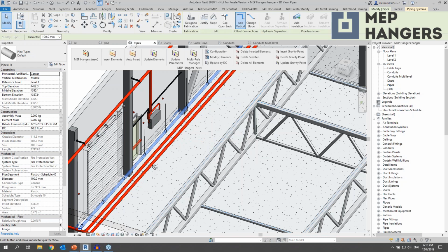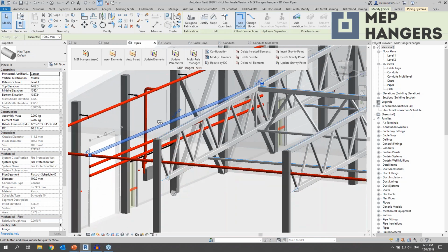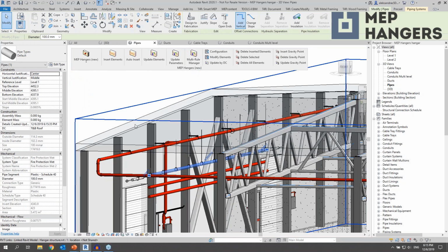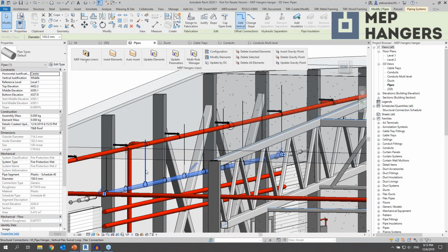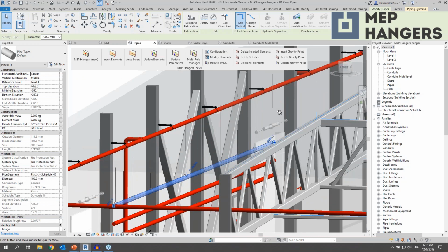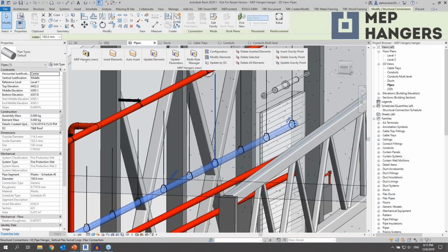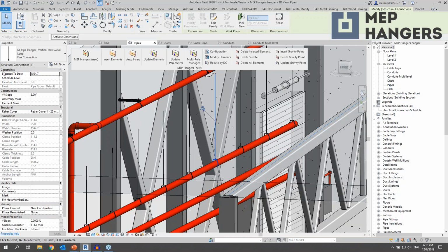And all our hangers are made such that, as you see, the roof is with inclination, and all the rods are getting longer and longer. So our tool finds that distance and writes it down into the hangers. It's called distance to deck. You can see that distance here.